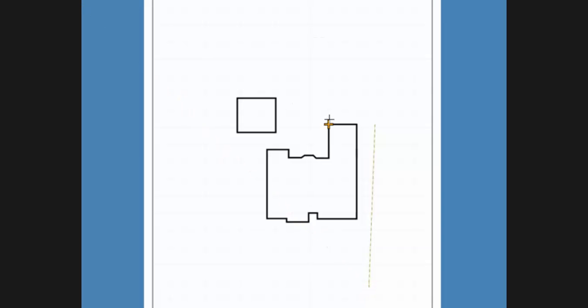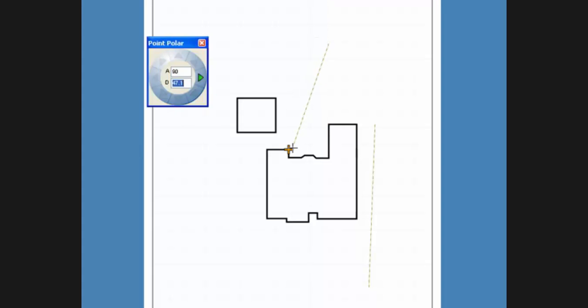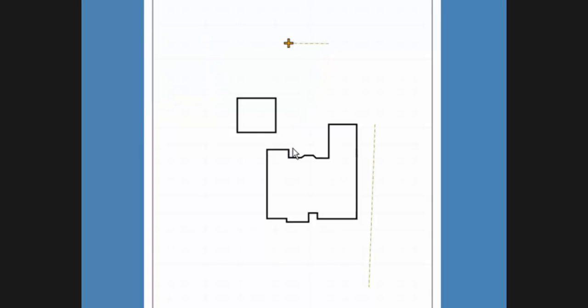We will continue to reset the anchor point location and use the point polar and point relative commands to draw line segments on each side of the house. If you measure out from the structures to any location on the property line, you can accurately draft the property lines on any plot plan. When using the point relative command, enter values moving to the left or below the anchor point as negative numbers.